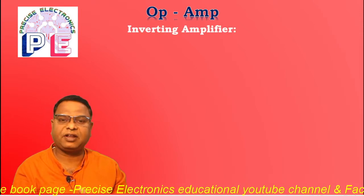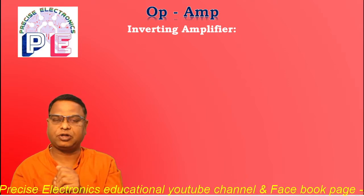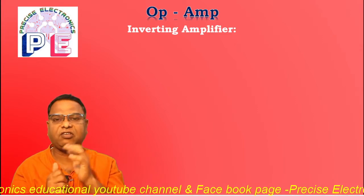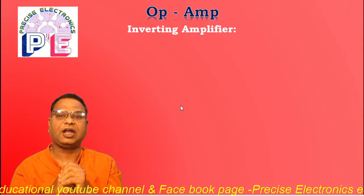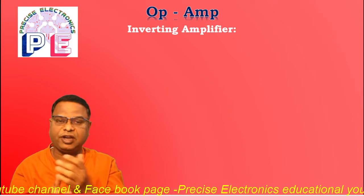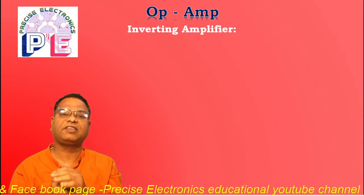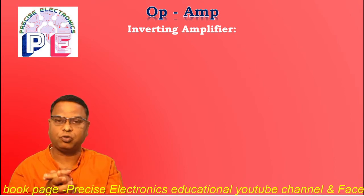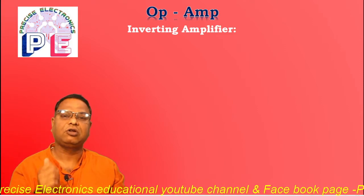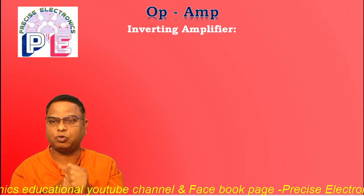What is inverting amplifier? Op-amp has two input terminals, that is the inverting input terminal and the non-inverting input terminal. If input signal is applied to the inverting terminal, this amplifier is known as inverting amplifier. And obviously in case of inverting amplifier, output is out of phase with the input, because this amplifier is used to invert the input signal. So output is exactly 180 degree out of phase with the input. If input is positive, output will be negative, and if input is negative, output will be positive. That means it is 180 degree out of phase with the input.